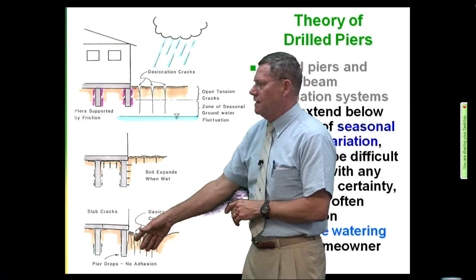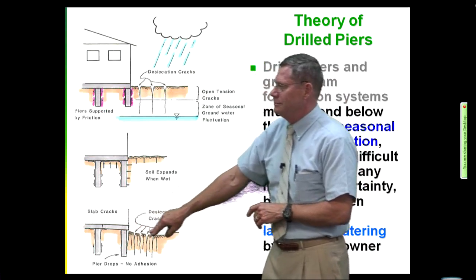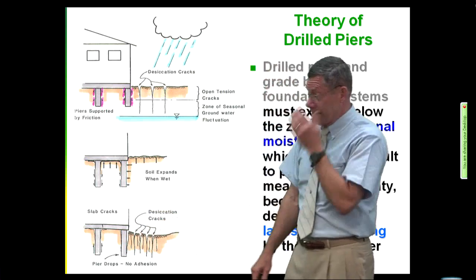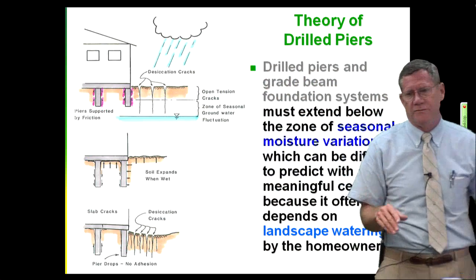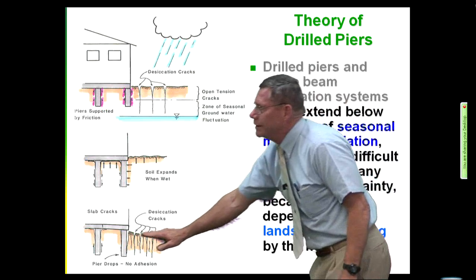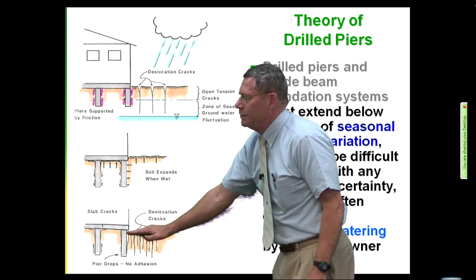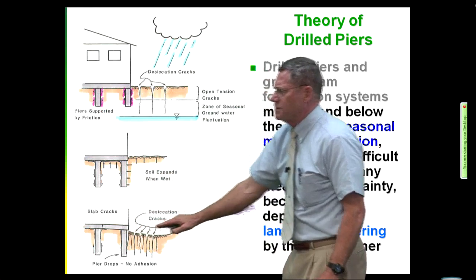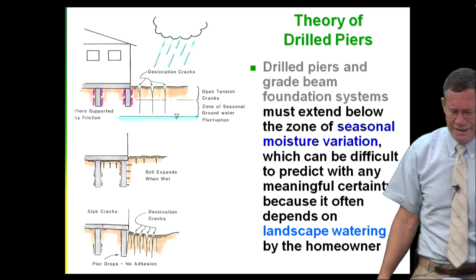And how do you solve something like this? Go in here and put some soaker lines in and heave this back up. You see this happening. My dad used to do that all the time. He'd go out there, somebody would call and complain, and he'd find, yep, they let one side of the yard just go fallow and get real, real dry. What you do there is you come in and bring this back up, even if you're under the house, and then you seal it off with something like visqueen so that you aren't going to lose all the moisture out of it again.